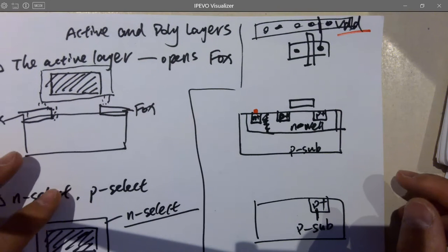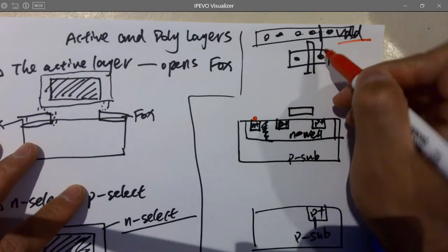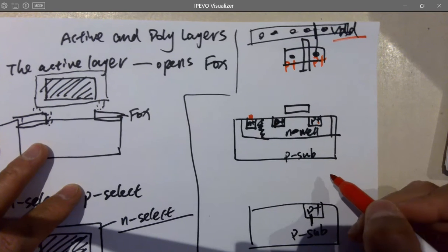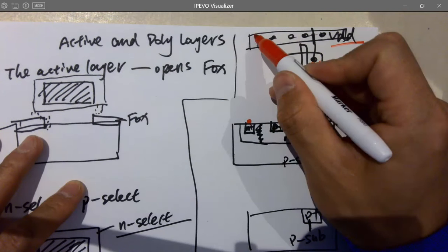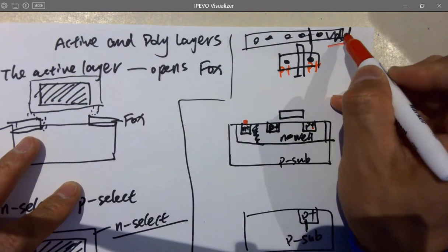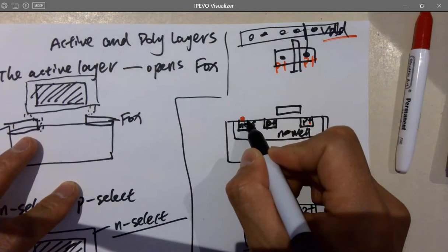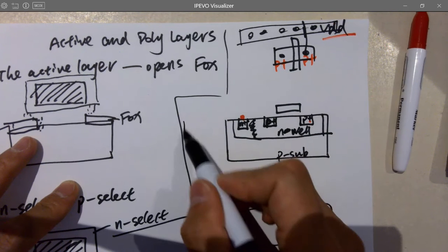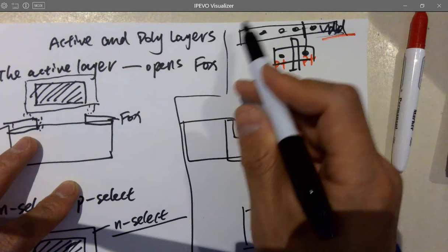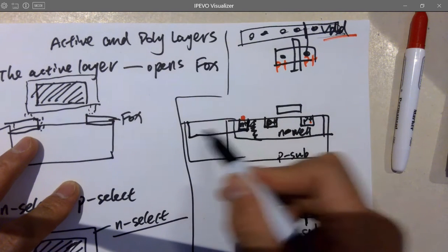So here's the question: why should we connect that one to VDD? So here's a PMOS, right? So the P plus over here, and that one. It's a pretty long rail actually. So on the wafer, how do I want to draw it? For this one, it's going to be this, right? A pretty long N plus.